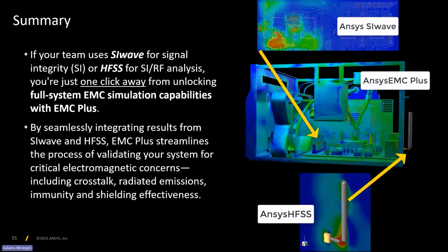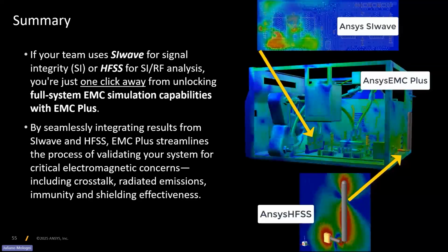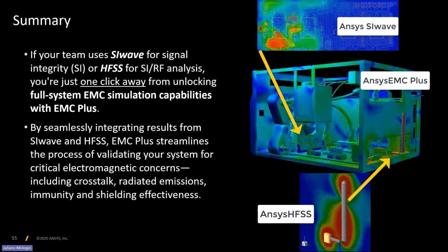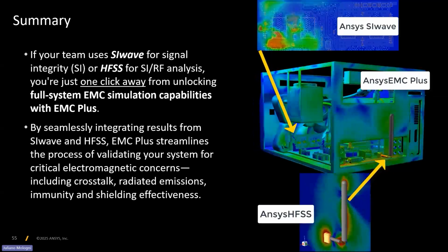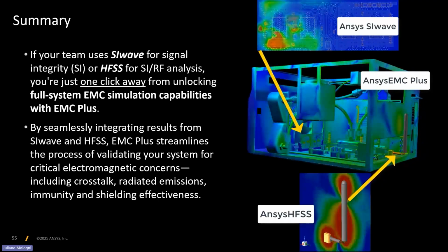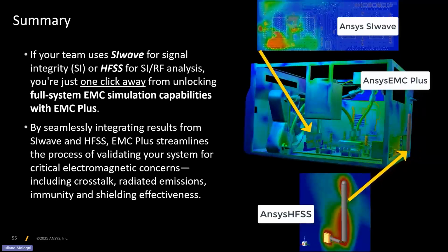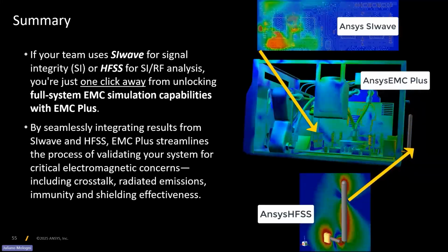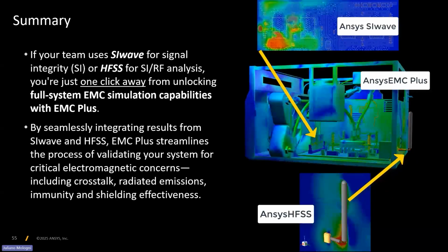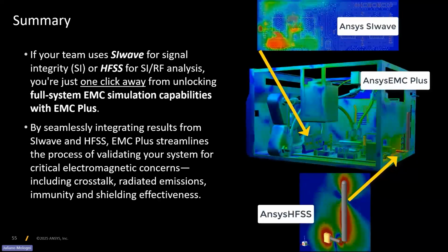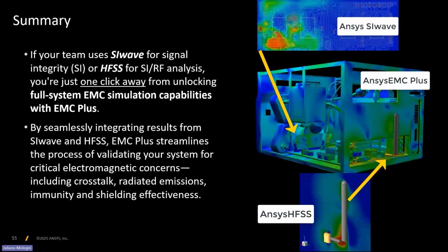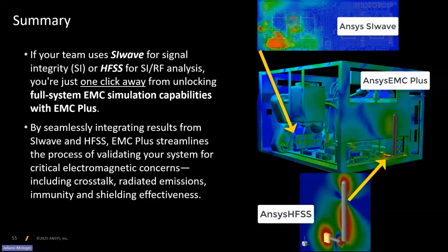We have some of the standard waveforms, and we have some sources in circuits that you can create. You have plane waves where you can provide a plane wave time domain waveform. But if you have a waveform from your scope, or a table in an Excel spreadsheet like time, amplitude, it doesn't matter if it's current or electric field, we can use it. There's no limitation. We're very flexible with regard to the input of the simulations.